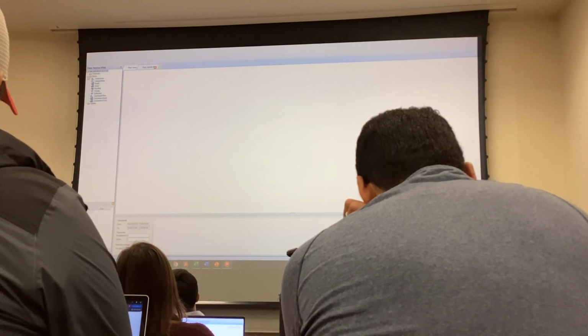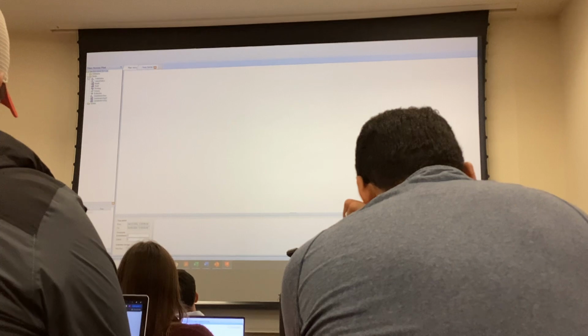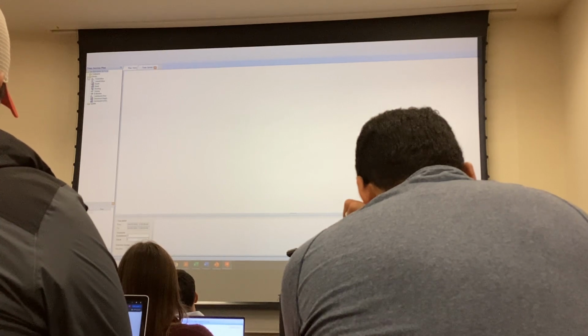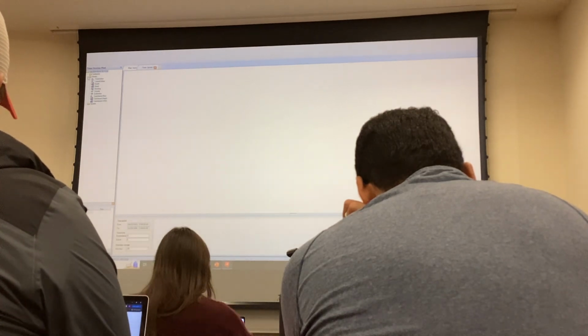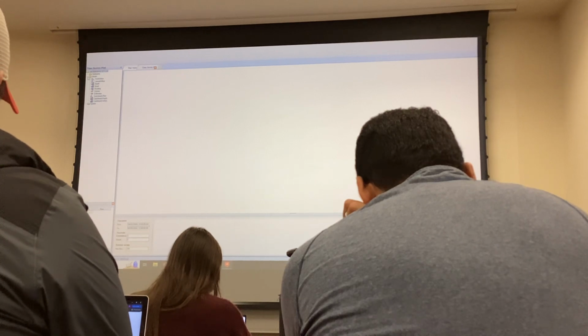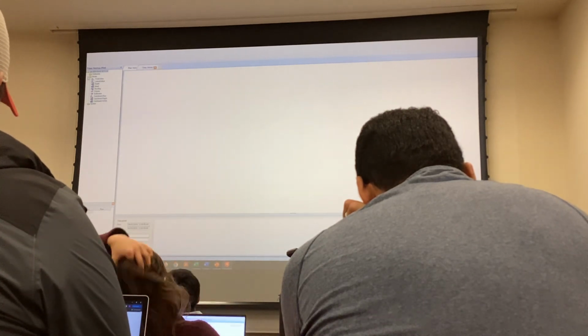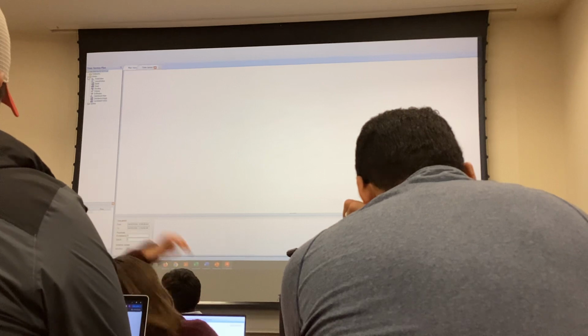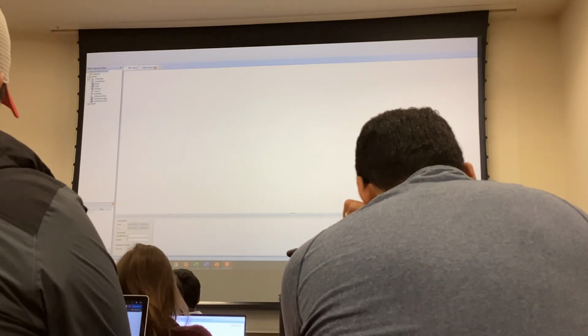Okay, so first of all, I haven't specified my outflow structure, right? As far as what the elevations are, all this, I only specified the maximum allowable flow rate. The way that this is done is it automatically gives you a volume.